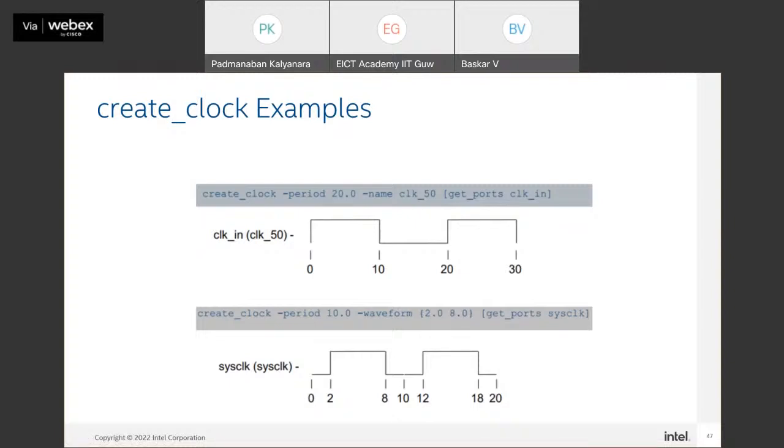We'll stop here, and then I will walk you through the next section, which is applying the timing constraints in the Intel Quartus Prime Timing Analyzer. Let us approach that method and then we will come back to the session. So what's the takeaway? You can see how we create the clock, and we are also going to see how we ensure the clock is taken into account with report clocks, and how we analyze the timing report, which is called report timing.